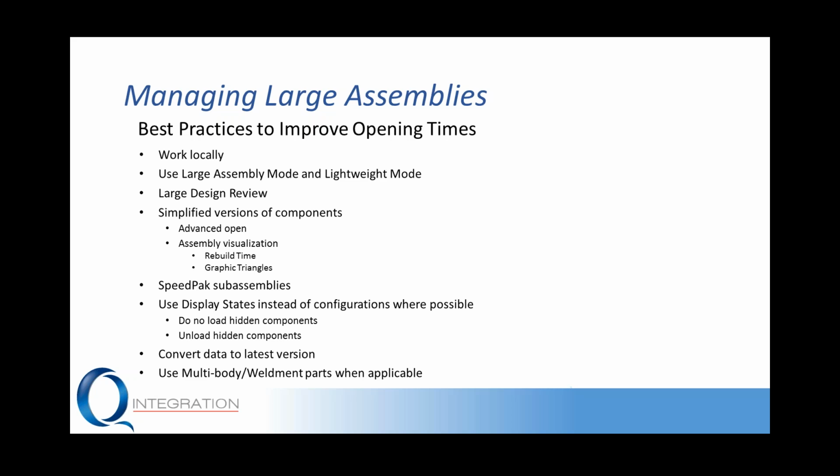SpeedPack sub-assemblies is the lightest form of a sub-assembly that we can create. And really I recommend, if we are using some purchased parts or purchased assemblies in our top level assembly, we want to create a SpeedPack configuration for those, because those assemblies aren't going to change. And if there's a lot of detail that goes into those assemblies, it's just more information that needs to be loaded up by SolidWorks each time we load that top level assembly up. So we can utilize SpeedPacks for those purchased components that we download online.